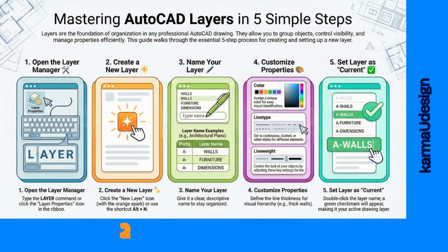And what's crucial here is to recognize that you shouldn't just draw on layer 0 and then decide later where things belong. That's the amateur move. Right, the cleanup after the fact approach. Exactly. A professional CAD workflow demands that you classify the element before you draw it. Yeah. So that blank line isn't just a placeholder. It's an immediate demand for clear semantics.